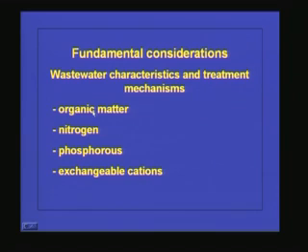become non-usable. Okay. And similarly, if the nitrogen concentration is within the permissible limit, it will be acting as a nutrient for the plant. But if the nitrogen concentration is very, very high, what will happen? The ammonia nitrogen has to be converted to nitrate. But if sufficient oxygen is not there, nitrification will not be proper.